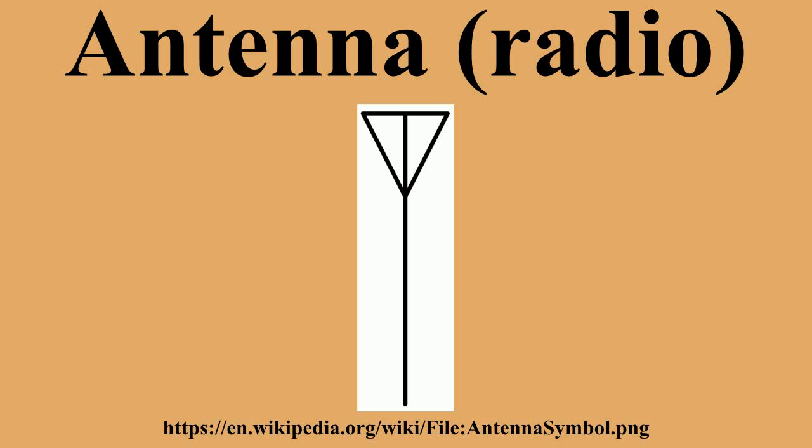However, a log-periodic dipole array consists of a number of dipole elements of different lengths in order to obtain a somewhat directional antenna, having an extremely wide bandwidth. These are frequently used for television reception in fringe areas. The dipole antennas composing it are all considered active elements since they are all electrically connected together. On the other hand, a superficially similar dipole array, the Yagi-Uda antenna, has only one dipole element with an electrical connection. The other so-called parasitic elements interact with the electromagnetic field in order to realize a fairly directional antenna, but one which is limited to a rather narrow bandwidth.